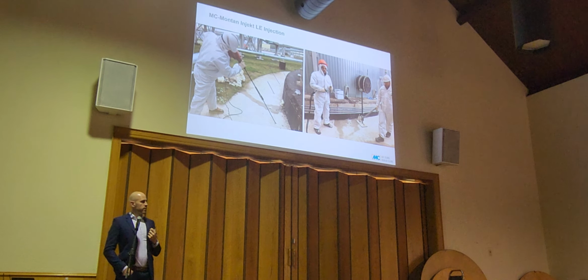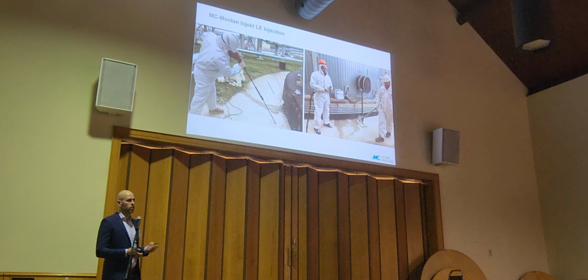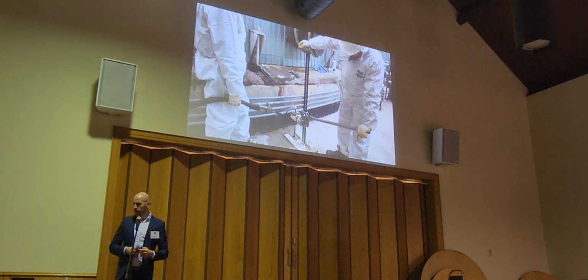This was a job site, so no big drill rig, no big silos for cement, nothing. Just, again, same equipment, steel pipes, a jackhammer, and what you see here is the horizontal thing, so the step 2. And here what you see in this picture is step 1, and they're using a jack rack. So they didn't use a pneumatic tool or something, they just said, okay, we modify this jack rack and use it to lift, to pull out the lances. Short video about that.